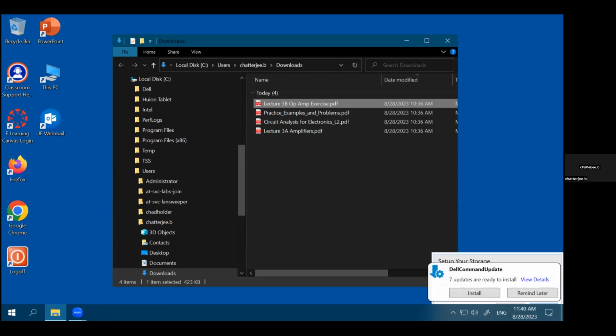The RMS is something with which you can represent the AC signal. The peak amplitude is something with which you represent the AC signal. The peak to peak is something with which you represent the AC signal. All of them talk about the same thing. The DC should be different, right? So again, the AC signal could be 1 millivolt peak, it could be 2 millivolt peak to peak, it could be 0.707 millivolt RMS. All of them represent the same signal, but it does not say anything about the DC. The DC is something that we are interested in. That's the bias we are talking about. Is this 1 millivolt on the 2 sides of 500 millivolt, or on the 2 sides of 0 millivolt, or on the 2 sides of 700 millivolt? We don't know that, but that's very important for this amplifier to work. Maybe let's take the question outside because there is another class.